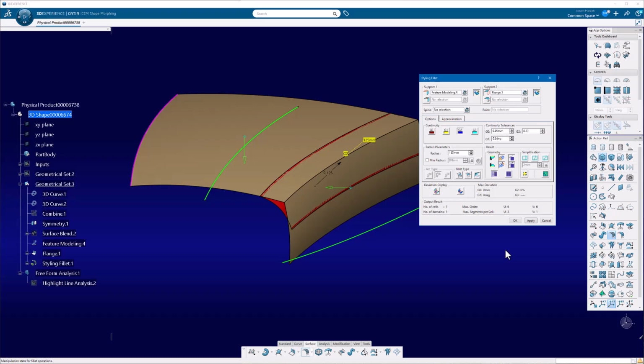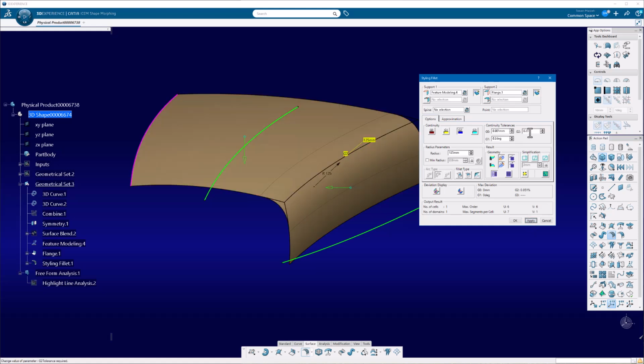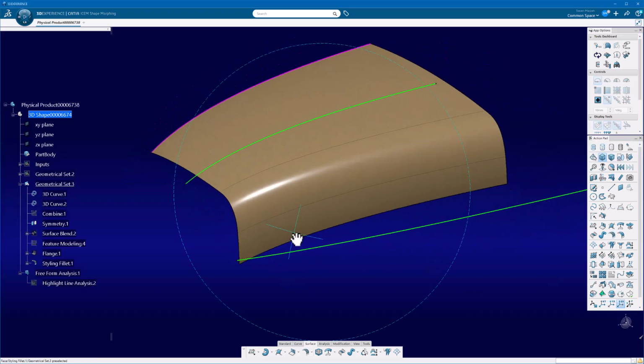And if I really, really want to, I can play around with tolerances, and I don't really, really want to. Now, if I take this and say, all right, well, my distance tolerance really has to be tight, because I know some places like to have a very, very tight distance tolerance, which, quite frankly, I do not blame them. You may slam this down. The old Chrysler days, it was 0.001. This is I think 0.1. It really doesn't affect this too much, but you see max deviation, everything is just perfect. And I'm going to select OK. And I got my blend on there.